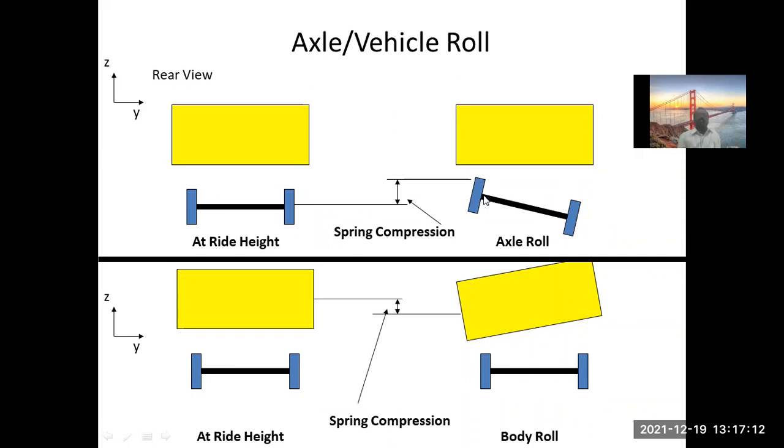Now the next type of motion which is being taken care of by the suspension system is the vehicle rolling. Rolling means when the vehicle is moving like this or this. Preferably you can experience the rolling when the vehicle takes a turn. You can see on the one side it moves up and the other side it moves down. Such a condition is what you call rolling.